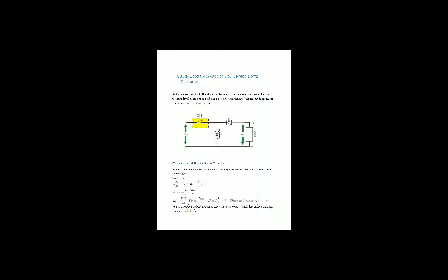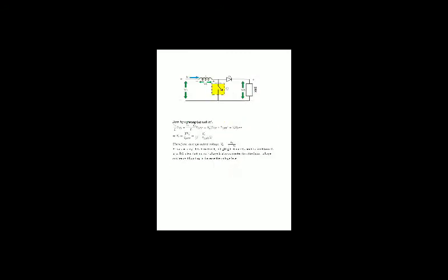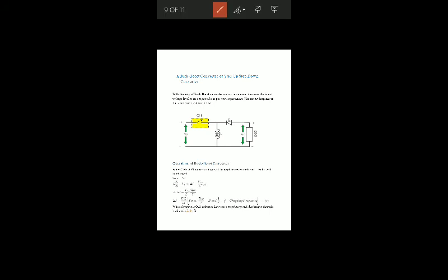In the step up down chopper, the buck boost converter, the position of the switch and inductor is interchanged and the polarity of the diode is also interchanged. You can see here. Similarly to the previous two cases, the study of the buck boost converter also remains the same. First we compute delta I for T on, then we compute delta I for T off, and you get these two equations, from which we compute the V naught value. With the help of a buck boost converter, we can increase or decrease the input voltage as per our output side requirement.